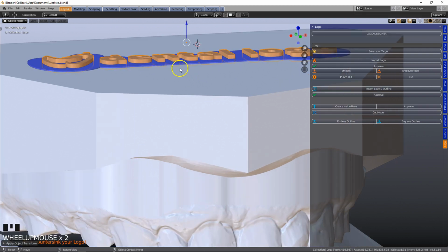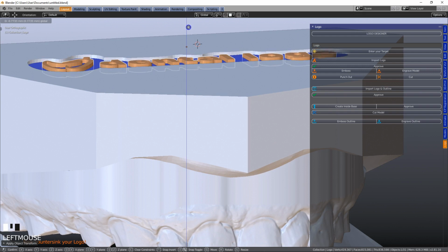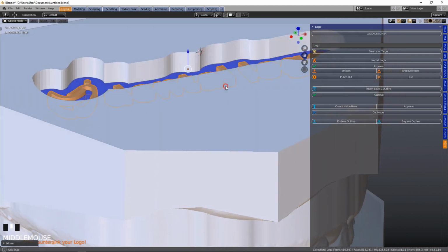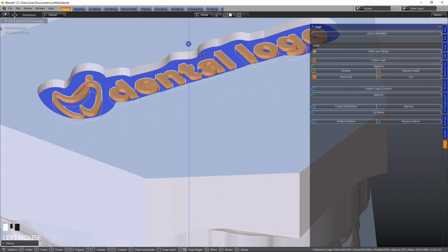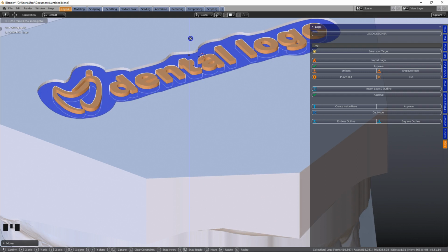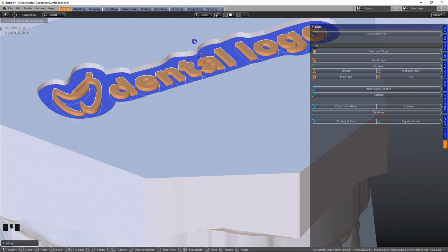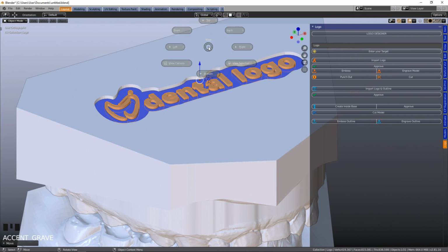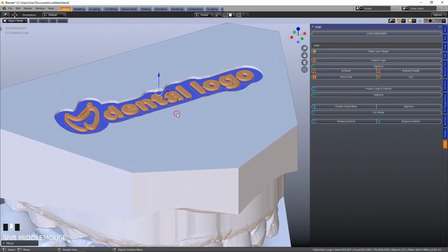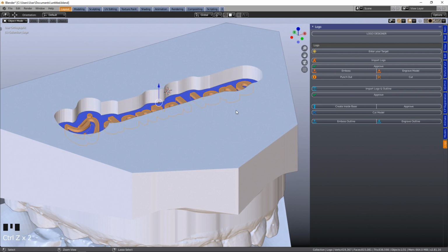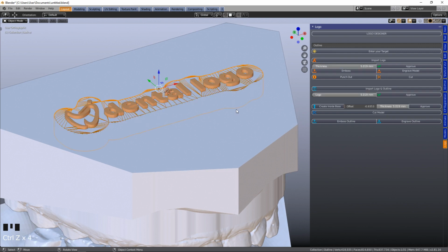This will now take the blue structure and it has cut a model on the inside. Now obviously that is the depth of the cutting tool, so we're going to set this, and then from the front view we can then set it flush with the surface of the top of the base, and then we can either emboss or outline. Now I'm going to take this one step back and we're going to make a honeycomb from here.